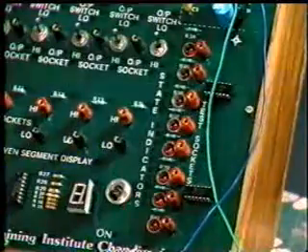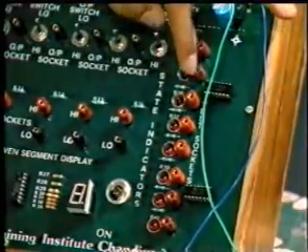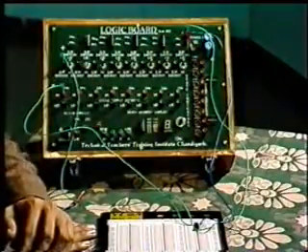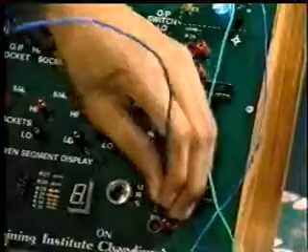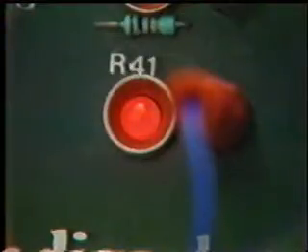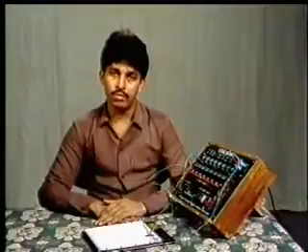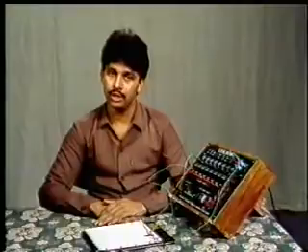The logic board has 8 test sockets, each of which is connected to LEDs. Connect the output of the NAND gate to any one of the sockets. The glowing LED indicates that the output is high. When the output is low, the LED will not glow. For this circuit, we conclude that when the variable input is at logic low, the output is logic high.